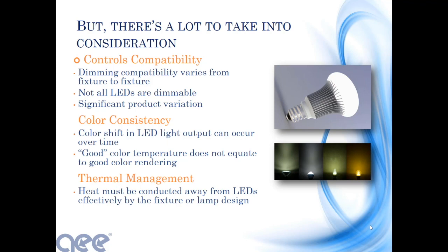Okay, some things that end up happening is if you get a fixture from a manufacturer one month, three months later, they may have changed their LED driver supplier. Okay, and then changing that LED driver supplier can change some of the things that Tanya was talking about as far as color and things of that nature. Okay, not all LEDs are dimmable, especially looking at residential and screw-in and those types of things that you get at the big box store. There is an upcharge for a dimmable screw-in LED. The majority of your commercial troffer and those types of replacements, a full fixture, those are dimmable. I'm not even sure if you could get just a switching 2x2 LED fixture anymore.